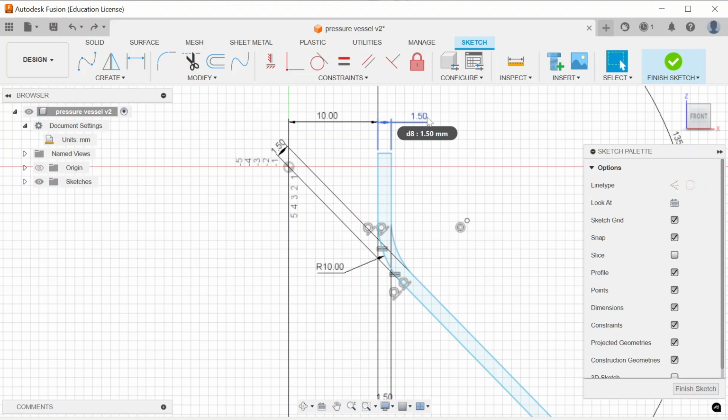I do not recommend going any larger than 1.5 millimeter wall thickness, nor do I recommend going any lower than 1 millimeter on your wall thickness. 1 millimeter or less has the potential of failing. 1.5 millimeters of 3D printed material is too much and it wastes time and material.